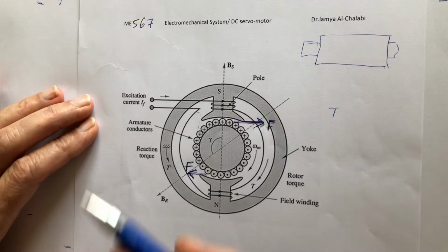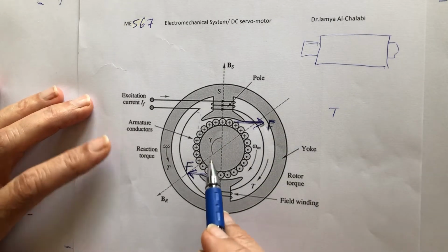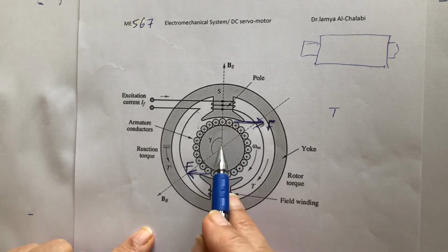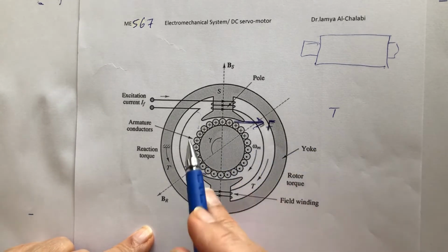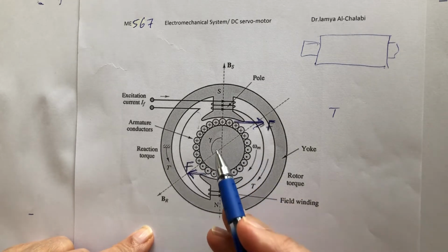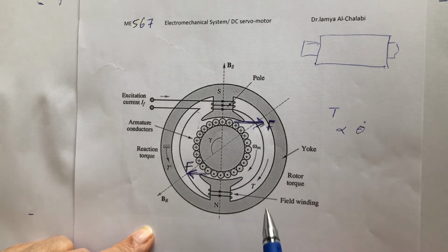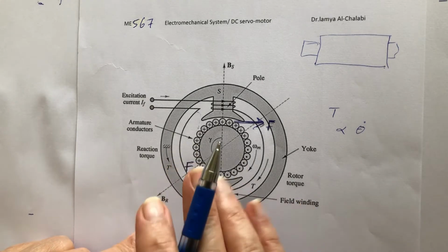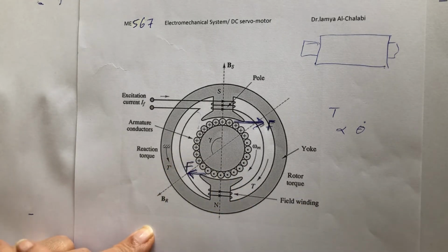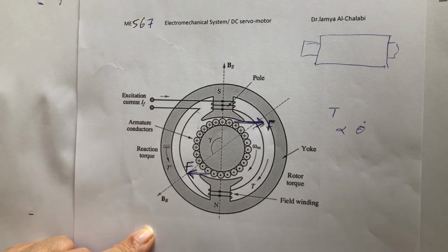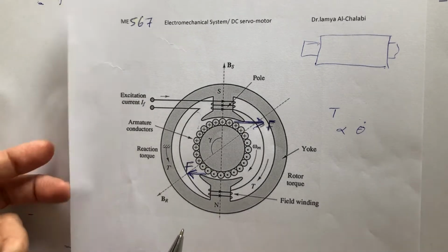So it will rotate like that. Let's say it rotates like that. Here we also have a current-carrying conductor perpendicular to the flux lines, so there will be a voltage. You remember it is proportional to theta dot, which is the speed, and of course the flux. Remember this when I make the schematic diagram and the block diagram; this is the simple construction of a motor.